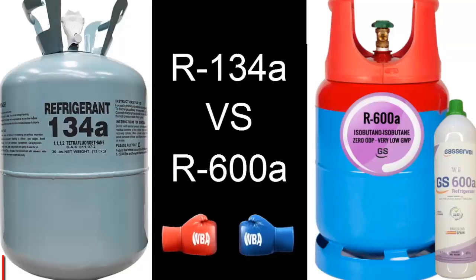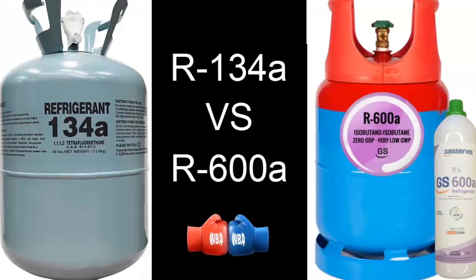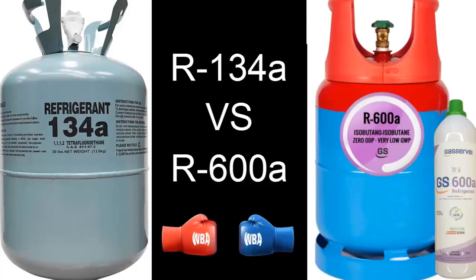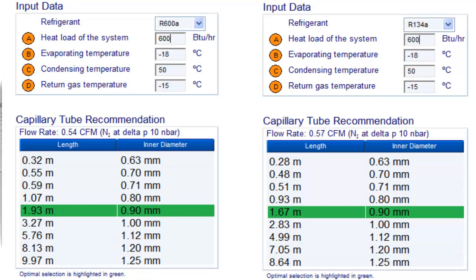Isobutane R600a, like other hydrocarbon refrigerants, generally has good miscibility with any type of lubricant, although in many cases it is recommended to use oils with higher viscosity. R134a is compatible with POE oil in conventional refrigeration and PAG oil in automotive air conditioning. On the screen, we have the tables of capillary sizes for R600a and R134a for the same cooling capacity.